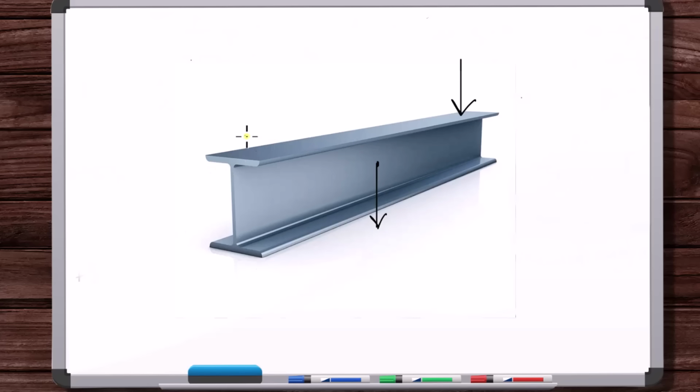But what about this, where we cut? This is a little different. This is not a bolted connection. There's no regions where a bolt was contacting the beam, or some sort of connection was contacting the beam. Is there contact here? Yes, there's contact. Contact between the material in this face and then the corresponding material that was on the opposite side. The area of contact is this entire cross-section.